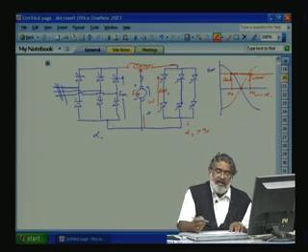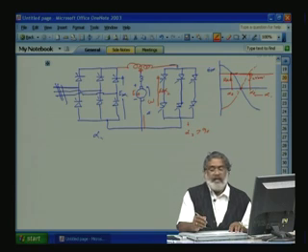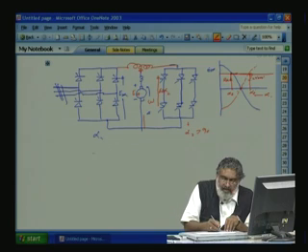Okay. Now, why this inductance? This is a dual converter in circulating current mode. See, we are talking about E01 and E02. The DC may be the same, but the instantaneous ripple may not be the same. Let us take a typical example, ABC waveform here.